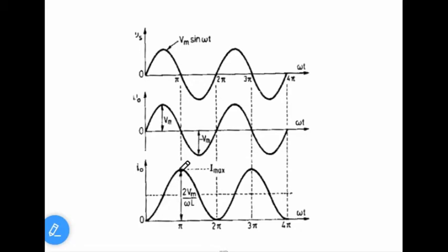After plotting that expression from the previous slide, I got a waveform like this. For one complete cycle of supply, I am getting one positive pulse. How did I get it like this? Because this is based upon the expression. Let us go with the conceptual answer. We know that voltage across the inductor, which is nothing but the output voltage, is equal to L into di by dt.